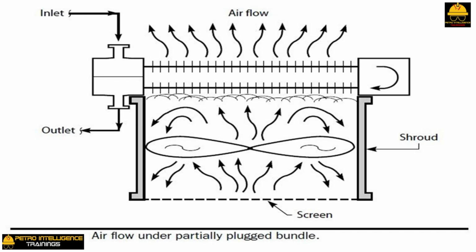As the underside of the fins becomes encrusted with dirt, an increasing amount of air is reflected back through the screen, located below the fan. The air is reflected back through the screen in a predictable pattern. The airflow in the center of the screen is always going up, which is the desired direction of flow. The airflow around the edge of the screen is always reversed, which is the wrong direction.